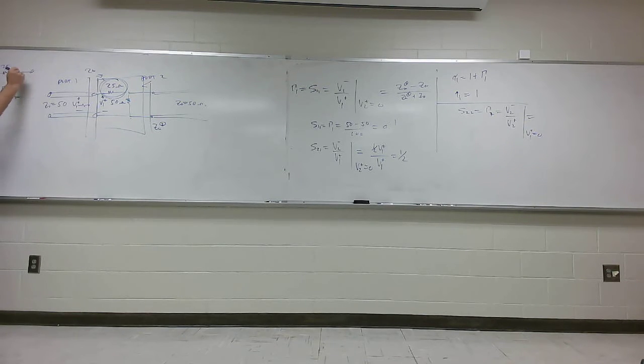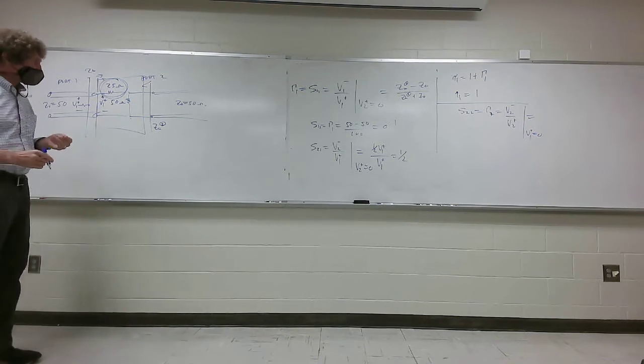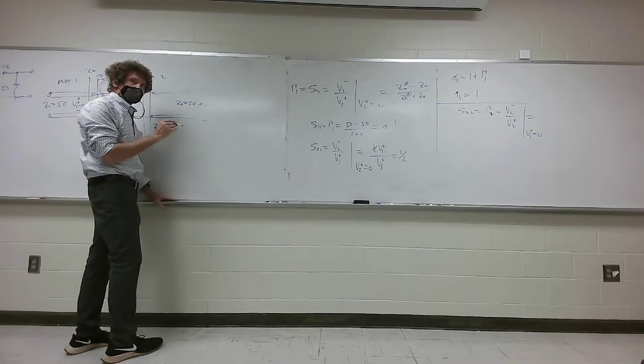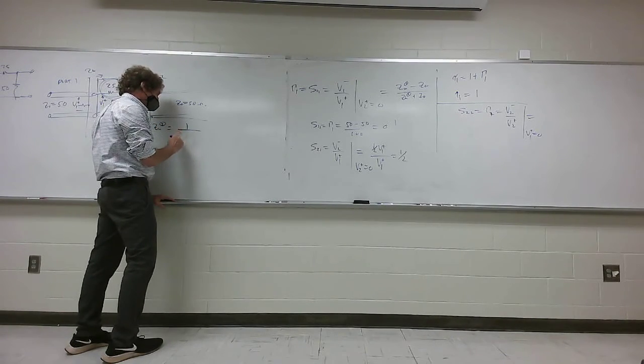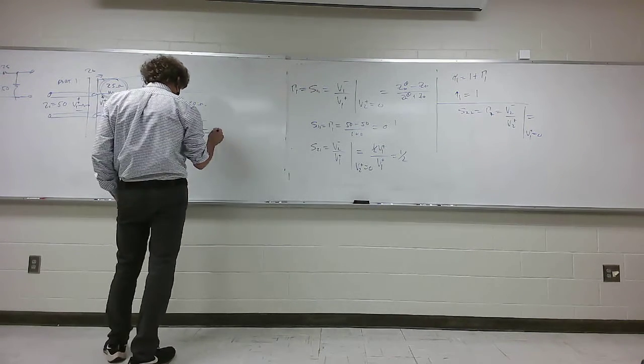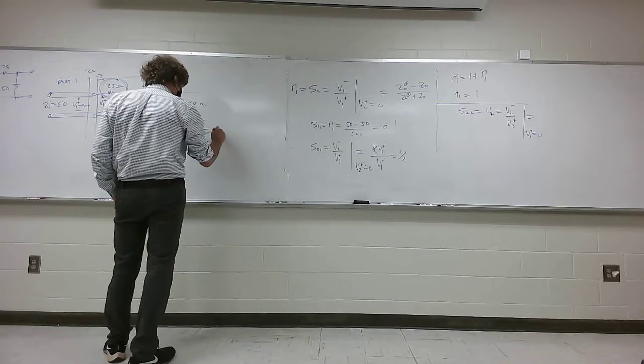And I want the input impedance across those two, so it's really 75 in parallel with 50. Do y'all see that? Class? Okay? So what's that gonna be? 30. You're right. It would be equal to 1 over 1/75 plus 1/50. And that will come down to 30 ohms.